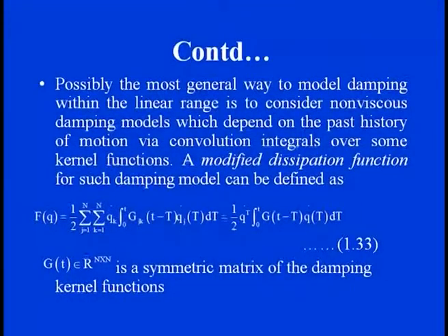The most general way to model damping within the linear range is to consider non-viscous damping models, which depend on how the system reacted to the force, or the past history of the motions, via convolution integrals over some kernel functions. So, then we need to adopt a different methodology for such cases.